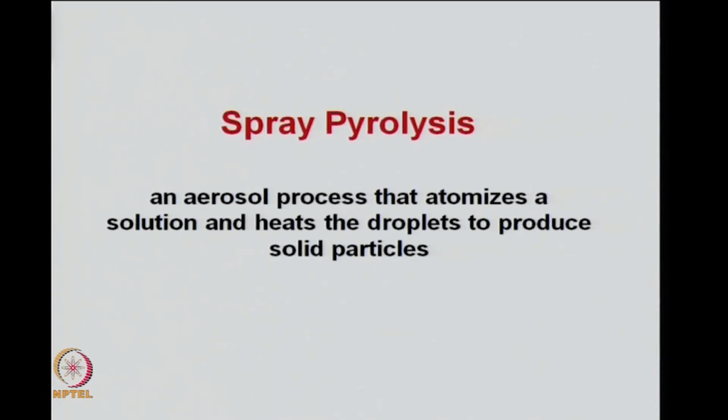From the words spray and pyrolysis, you can understand that something will come out as an aerosol and will then be heated to produce solid particles. Pyrolysis is the term telling you that something is going to be heated and it is going to break down the droplets into particles. Typically, spray pyrolysis can be defined as an aerosol process that atomizes a solution and heats the droplets formed by the atomizer to produce solid particles.